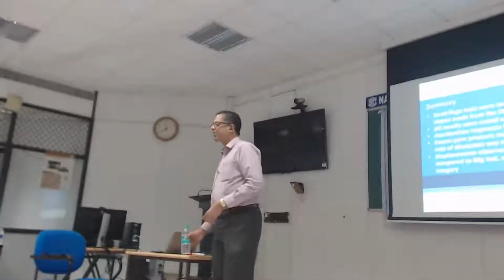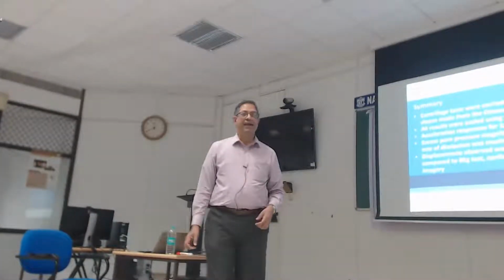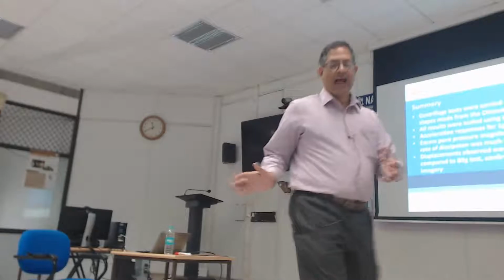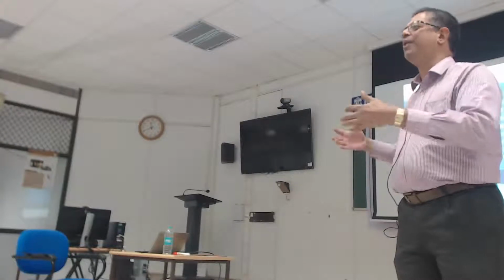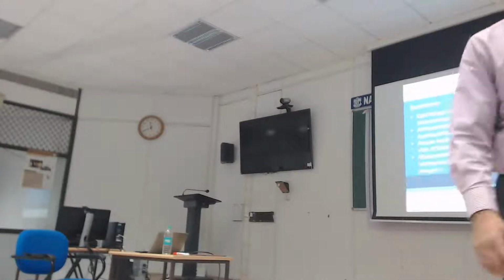At the moment, we're working on making a laminar box, but with a perspex front. So we want to combine our ability to do the lateral spreading, but with a view. Because this PIV business is too cute a tool not to use. And it really shows you where the soil is actually going.